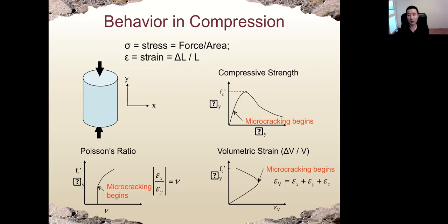When the concrete cylinder is under compression, initially the slope of the stress-strain curve is straight. But microcracking begins at around 30% of the final load. After microcracking begins, the slope of the curve becomes smaller until the final load, which is the load that makes the concrete fail. After that, the resistance of concrete to stress becomes smaller, but it can still resist some load until final failure.